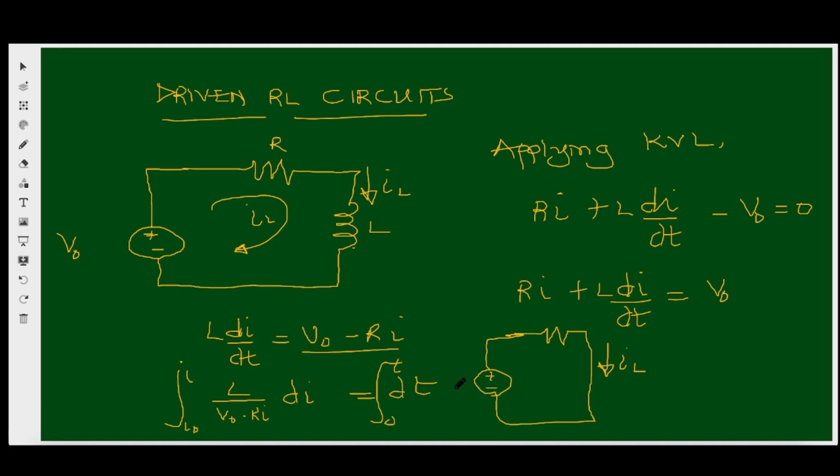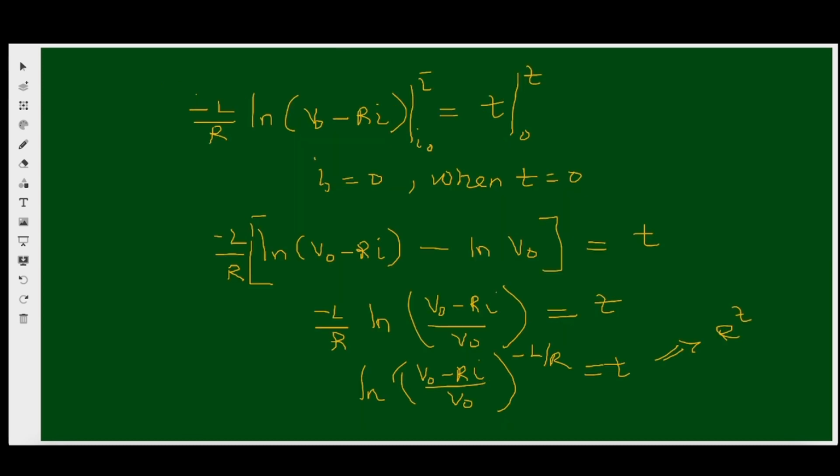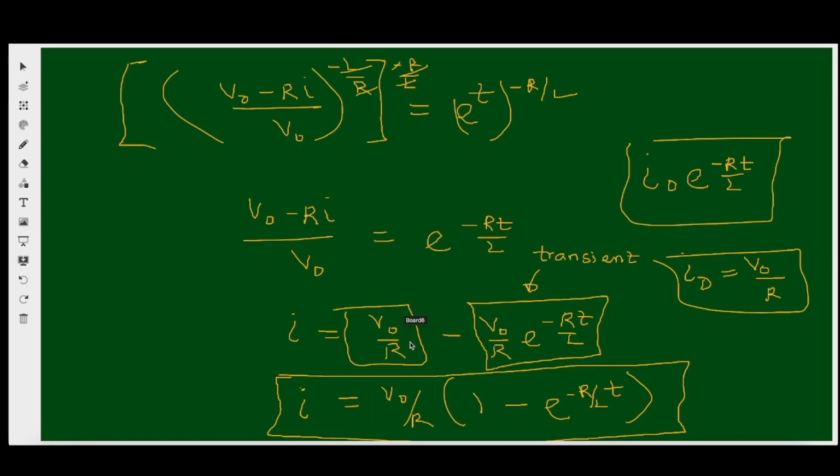So plus minus V naught. Because it is forcing it, it turns to a short circuit. So this is R, and of course I want to get iL. What would that be? iL will be equal to V naught over R. That's Ohm's law, straightforward. So this is the forced response, and you can see that that is what we have here. This is the transient response, and this is the forced response. As simple as that.